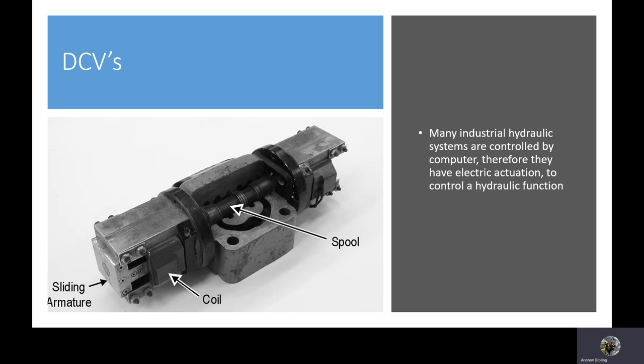Fluid cleanliness, of course, we covered before, is extremely important. And in a lot of these valves, particularly pilot-operated valves, there are a lot of extremely small passages that have to be kept clean. If they're not kept clean, the mechanisms won't work and the system will fail.